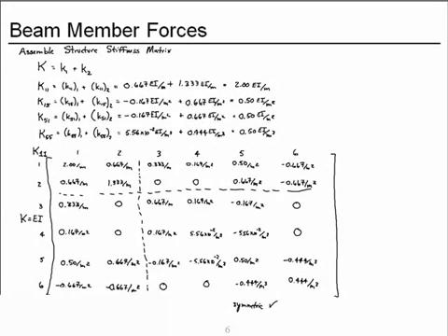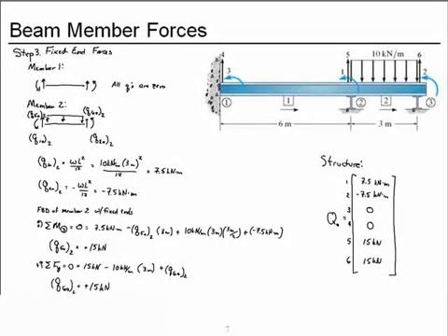We then partitioned the matrix after we confirmed it was symmetric as a quick check against math errors, and we identified the chunk K11, which is the coefficients associated with forces at unconstrained degrees of freedom due to deformations at unconstrained degrees of freedom. We then found the fixed end forces for member 1 and member 2, added those together by degree of freedom to get the fixed end forces for the structure.